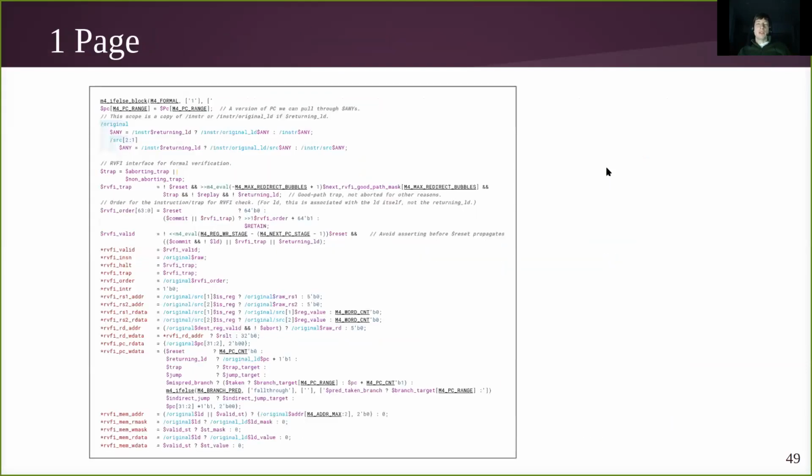So as promised, all of this test harness is created in a single page of code supporting all the variable pipeline depth implementations of RISC-V. The first couple lines here are the MUX. Then there are a couple lines of combinational logic that's providing information that needs to be presented to the checking that's not inherently already available as a signal in